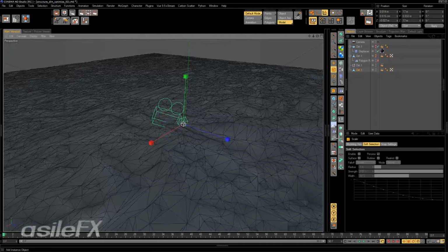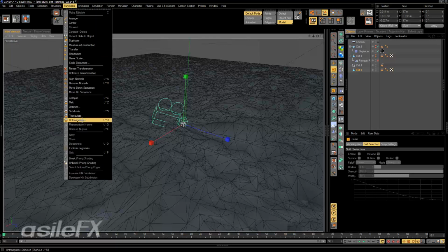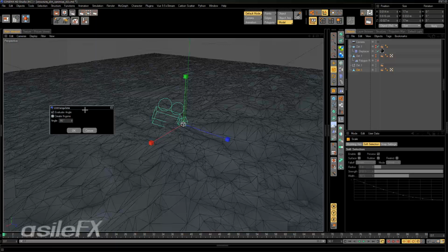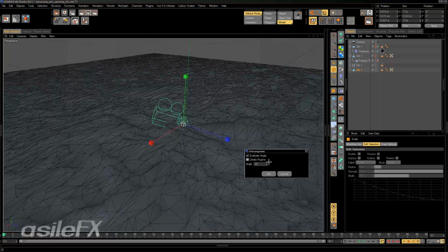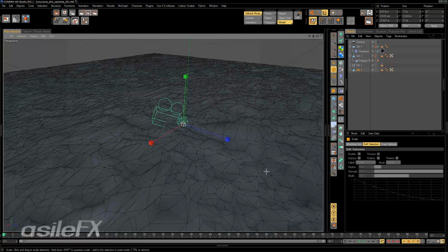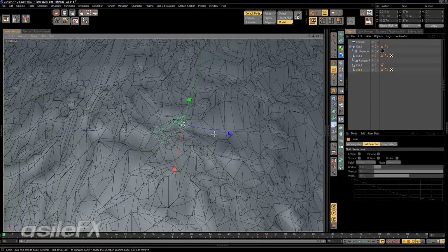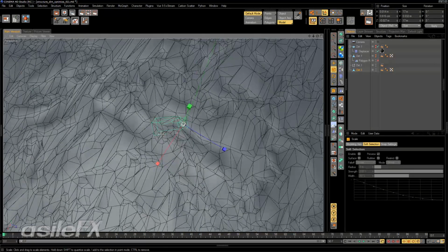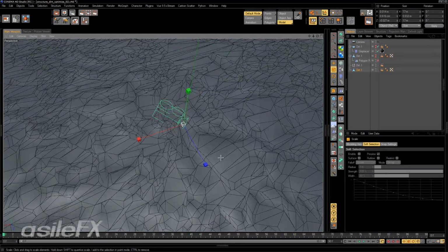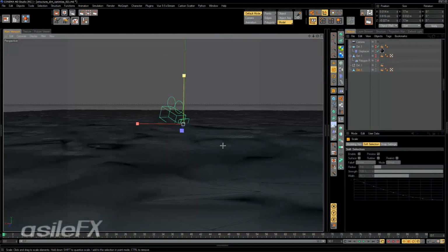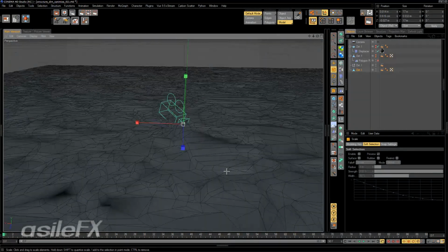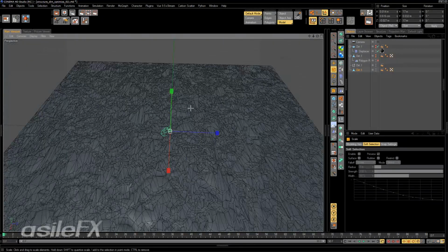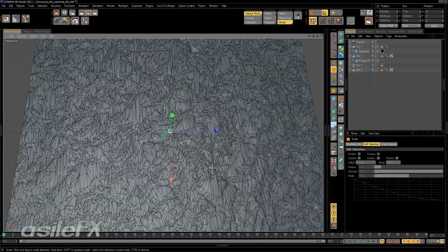One thing we can do is just turn off the n-gon creation, untriangulate, turn off that create n-gons. One of the easiest ways is to just turn off the evaluate angle altogether. Click OK, and it's just going to remove all of those triangles, or at least most of them. The ones you'll find on the steeper parts, steeper slopes, are typically going to remain, but this becomes a much more efficient object to populate on.